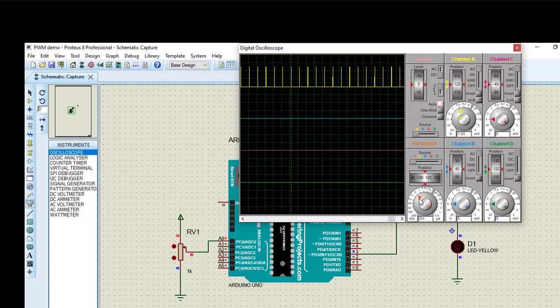Of course, you can see that there are actually several pulses that we're getting at the pin, as the pin is trying to toggle and switch on and off. This is the technique that, if you were to apply it in real life, uses pulse width modulation, and we can see that for sure we're able to achieve this pulse width. But I also want to mention it's difficult to see how we're changing the duty cycles here, because it's difficult to visualize it.